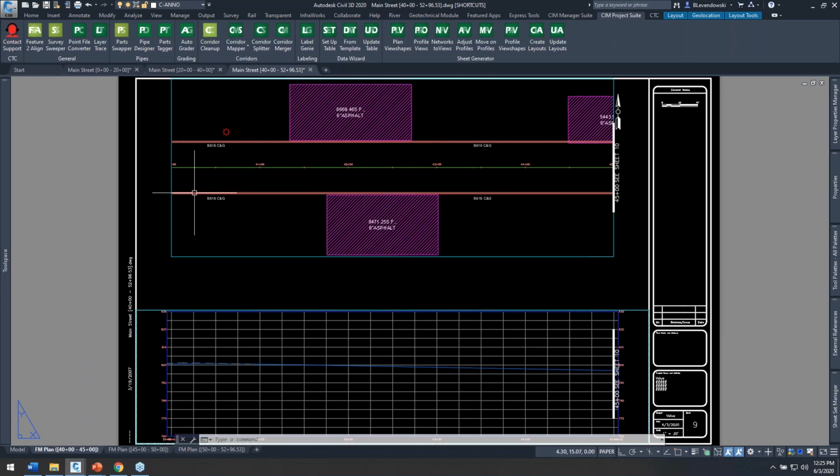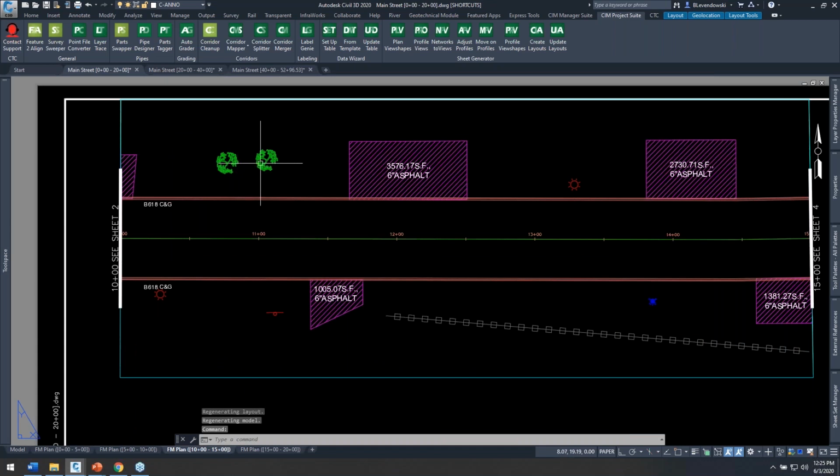Okay, so mtext callout on there. Let's label a few other things here. Let's put some M leaders out there. And I'm kind of focusing on some of these simpler AutoCAD objects, because in fact, these are the areas of such a pain point, right? There's almost no automation. What's the most automated Civil 3D label type that we have? It's probably pipe network labels, where you can choose an entire plan or profile view and add all those pipe and structure labels at once. That kind of functionality, we're bringing that to basically every other label type. That's what we're after here.